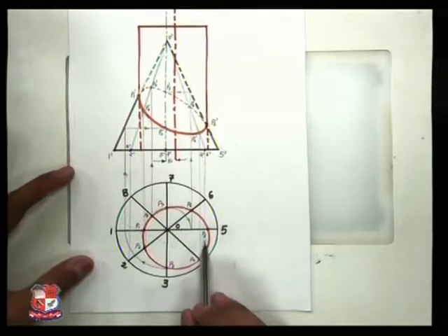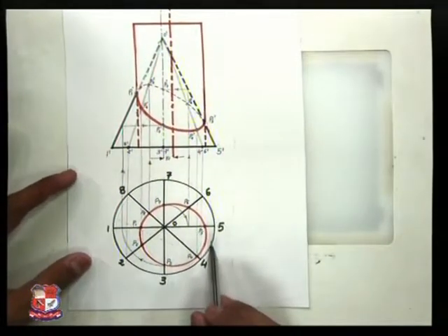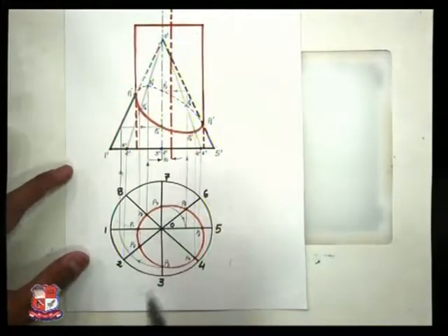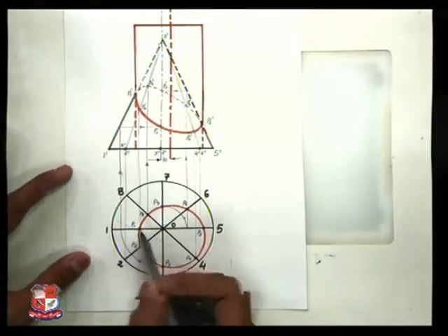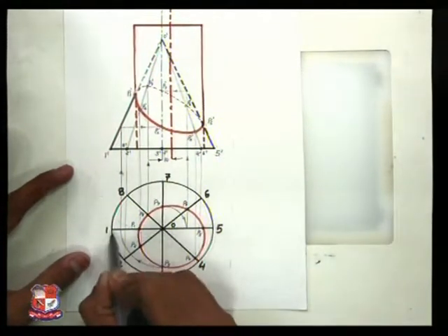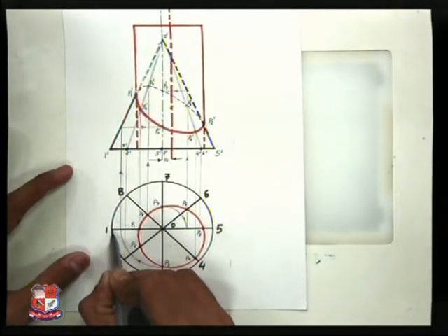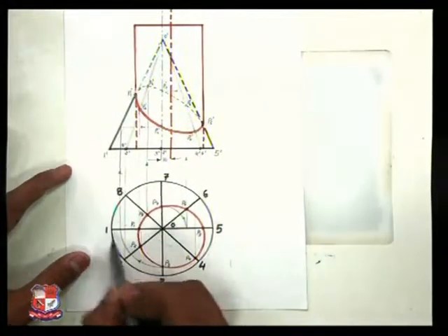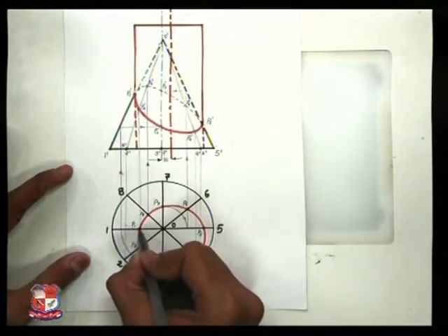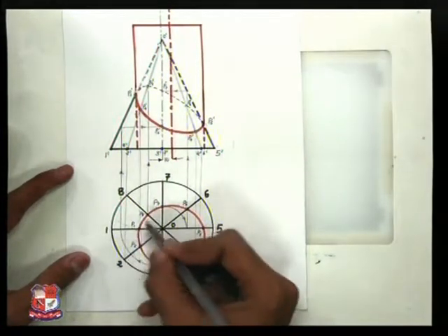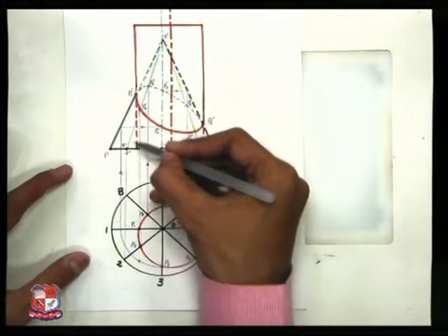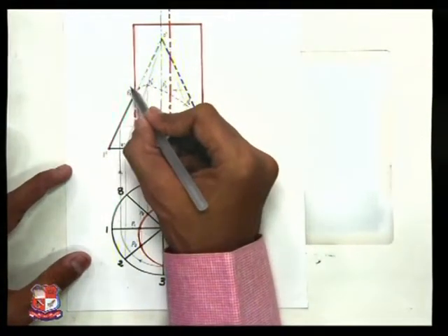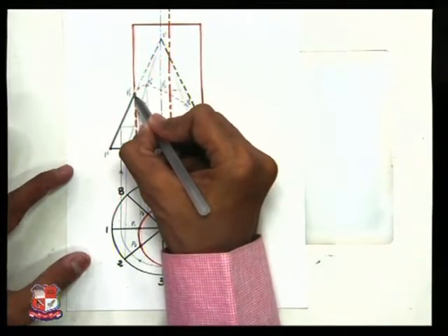After that, to find the points of intersection of both the solids, let me pick up points on the periphery of this cylinder. Suppose here is the point P1, which is on generator O1. O1 is the imaginary generator drawn over the cone, and O dash 1 dash is the generator in front view. Now this cylinder cuts O1 at this point, that is point P1. From this point draw a straight vertical line that will cut the generator O dash 1 dash at one point. This is P1 dash, that is the position of point P1 in front view.